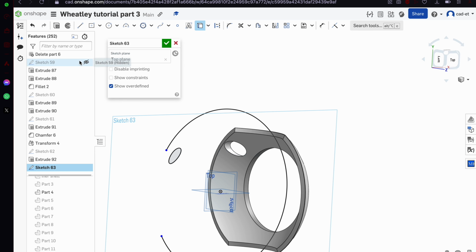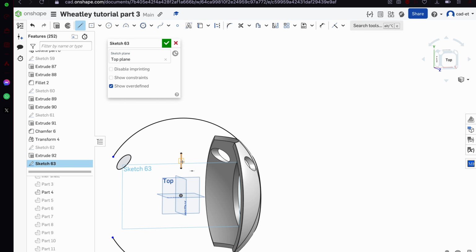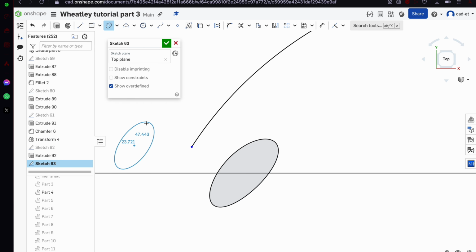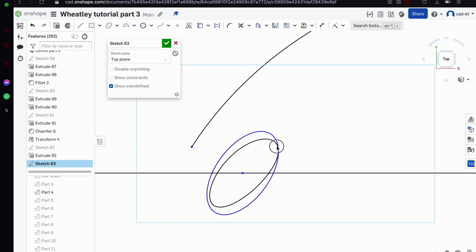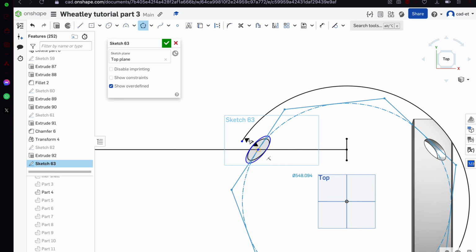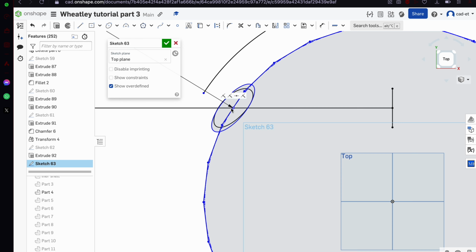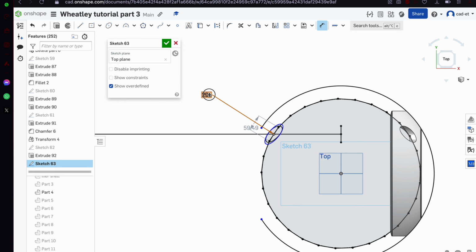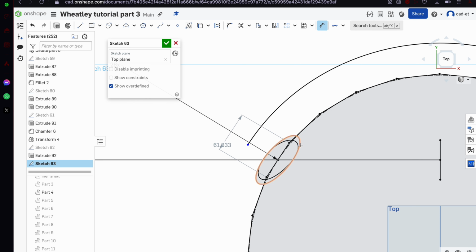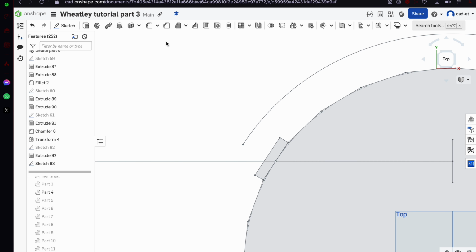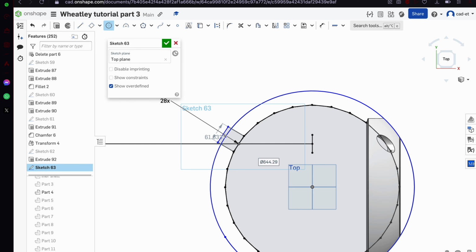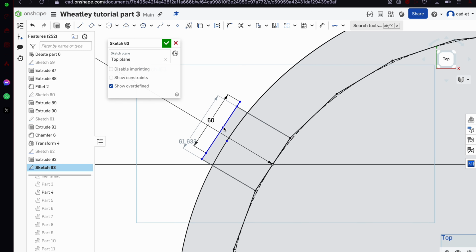I didn't realise this until later, so I had to use the branch off tool to flip the shell around and then bring the parts back out of a branch off with the shell flipped the right way, and then flipped everything after that into the right direction.